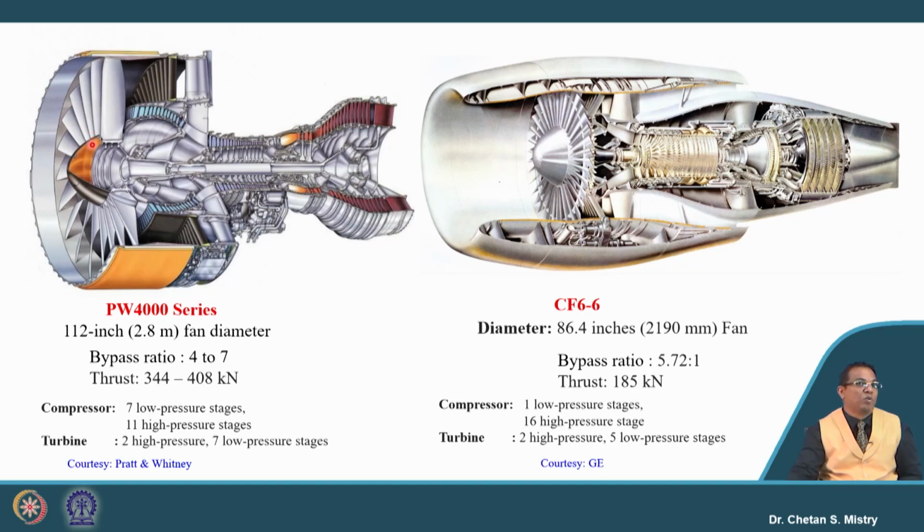That means one idea is to increase the diameter of the fan, and the second idea is to decrease the rotational speed of this wheel in order to achieve the same compression ratio. Here in this case, my diameter is coming to be higher, and aesthetically it is not that the engine is looking fine. Just realize how the designer has made his thought process. Since my rotational speed for this disc is lower, in order to achieve the high pressure ratio we have increased the diameter.